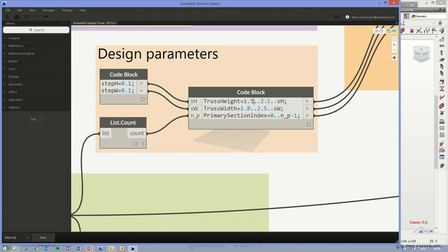You see, we have 121 members that are over-designed, which means their ratio is lower than 0.8. So 121 times 50 plus one time that overstressed member, which is 1,000, then you get to that 12,000 weight score value. That's the thing about that.